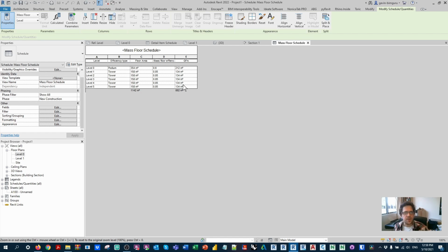So it's really handy when you're doing a super simple massing exercise, and if you don't have too many options with different floor-to-floor heights to manage. But once you do have different floor-to-floor heights, it can get quite complicated because, like you saw, you do have to tell mass floors which levels they use. So different options would lead to maybe different sets of levels. It can get really, really messy. You can use work sets to hide sets of levels, or filters, but it's still incredibly messy.